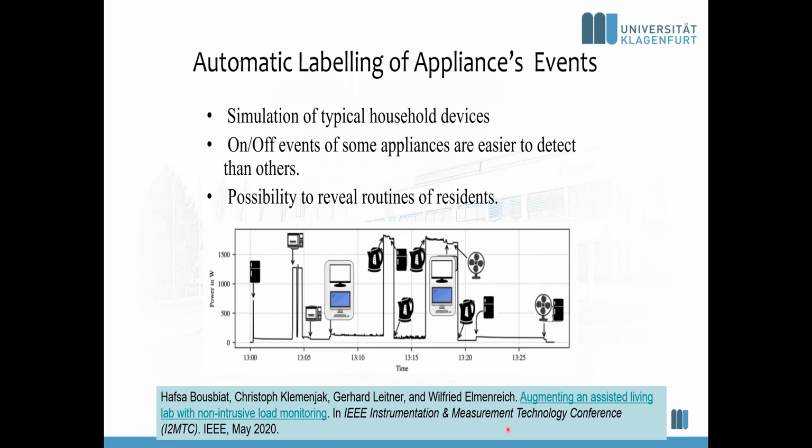Another thing for doing the disaggregation: we found out that values of, let's say, second granularity, so having a measurement every second, or even a little bit higher than that, like every tenth of a second or so, would be great to detect devices. But in the beginning of the talk, I told you that the smart meter has interval measurements of like 15 minutes or 1 hour or something.